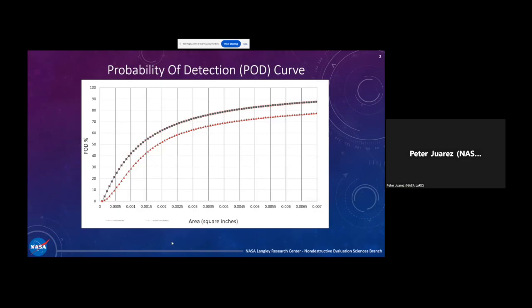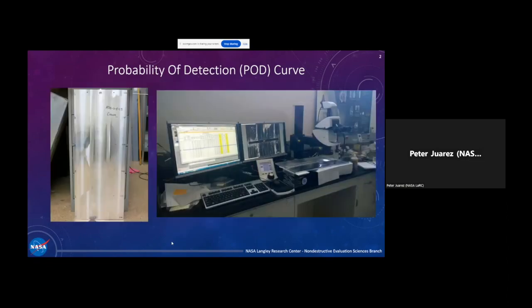And so when they were taking the data, like Star mentioned, you make a whole bunch of samples of representative geometry and representative material, and then you put a bunch of defects into those samples, and you spread them out in a design of experiment sort of way, so you get a statistical representation of a normal inspection in your experimental data. And so these were machined using electric discharge machining, which basically they plunge a wire that they run a lot of current through, and you can make these very fine line notches in your panels, and those are supposed to simulate cracks.